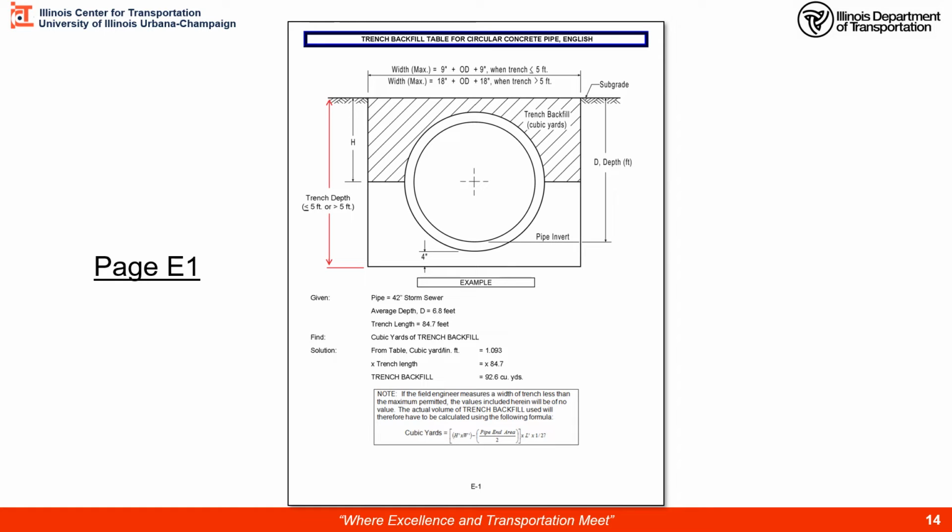That is measured from the invert of the pipe or the flow line to the surface of your excavation. By doing that, that will tie into the haunch thickness, haunch elevation above. So this is the area that we're going to calculate in the tables for trench backfill.